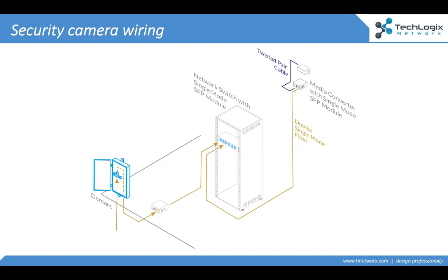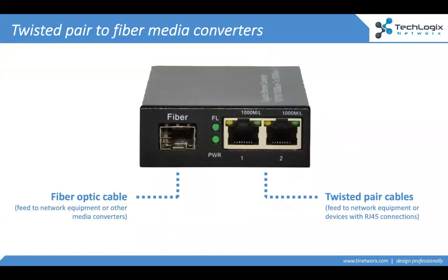And especially in a lot of these monitoring applications, we have to put a media converter in. What a media converter does is it takes the electrical signal and it converts it to an optical signal and vice versa, okay? They convert media. And by doing so, we can now take those electronics that maybe we bought a year ago that are really designed for RJ45, and we can drop them onto the fiber cable. And when we do that, we get to go really long distances. And now we have a cable that has the bandwidth to be upgraded to something else in the future. It's waterproof, tons of advantages as we've discussed.